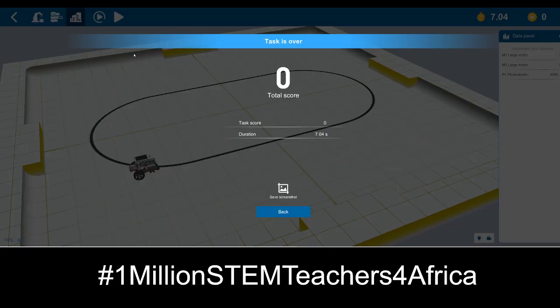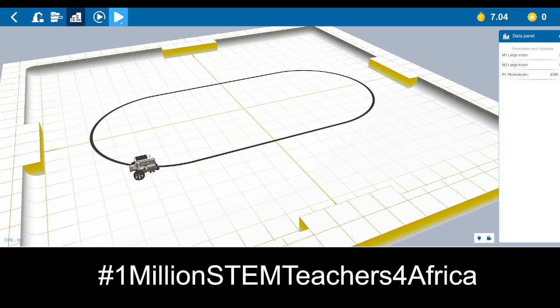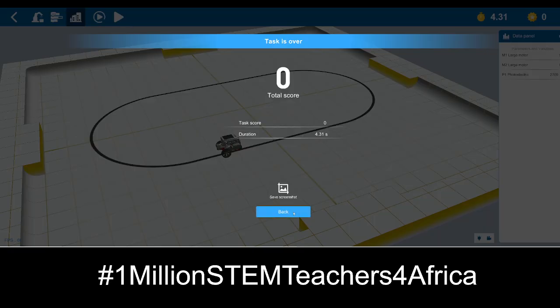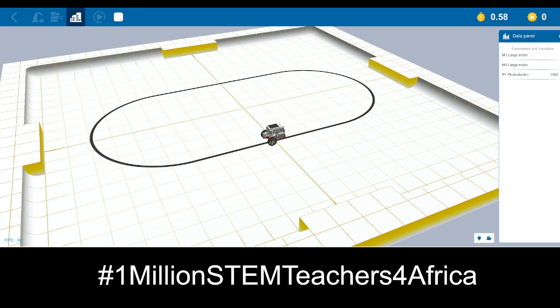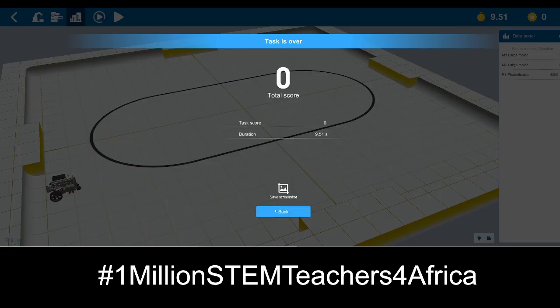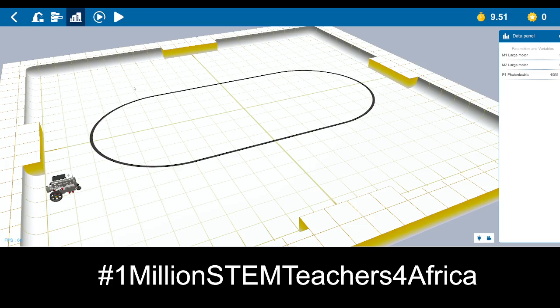So here, there is some error margin because I believe this robot is starting at a noise. Have a look here. It's reading 0. My robot is not seeing any line. But over time, because of noise and other factors, maybe it saw the line, then it started moving. And once it starts moving, there is no other code giving it the next instruction.